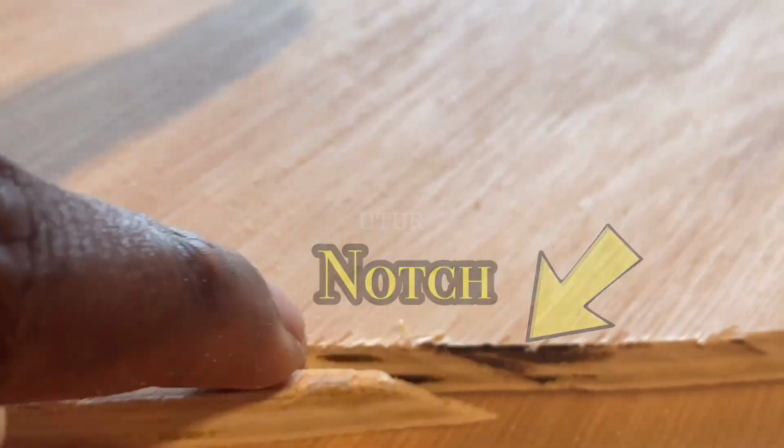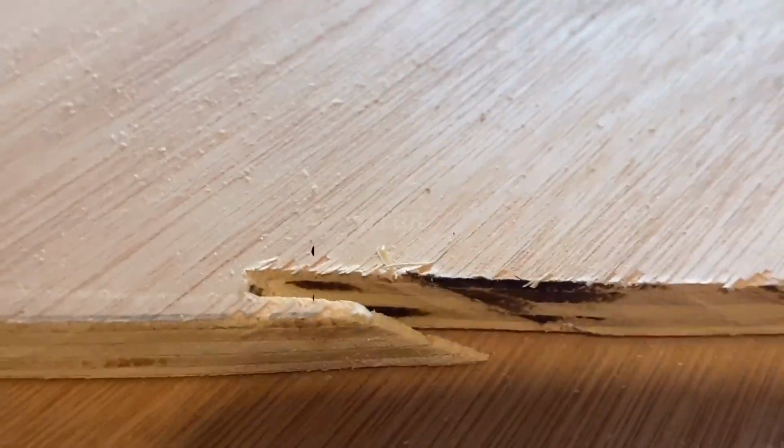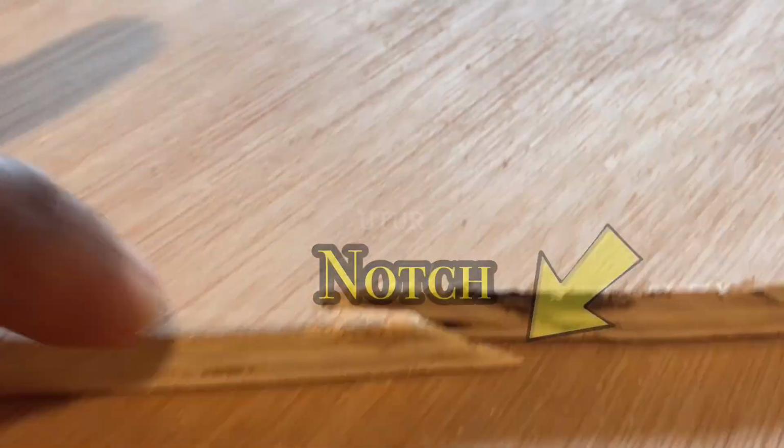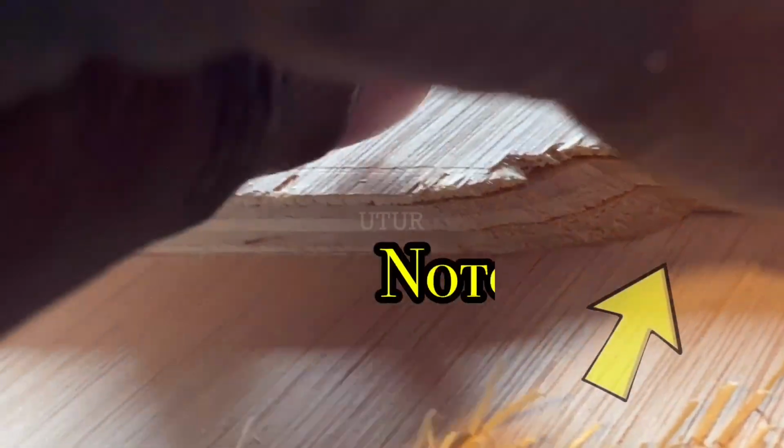So let's visually inspect the diagonal cuts to see if we've got fine quality cuts. And straight off, you can see that it's not a very fine or pristine quality cut. And there are a host of reasons why this has happened. Firstly, you can see that the blade bent at an angle. We kind of wiggled, and we didn't accurately have a continuous cut. It wasn't a linear cut. And as such, the blade bound in the sandwiched edges of the plywood.